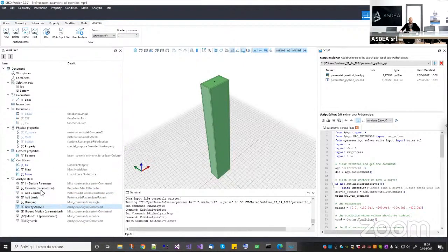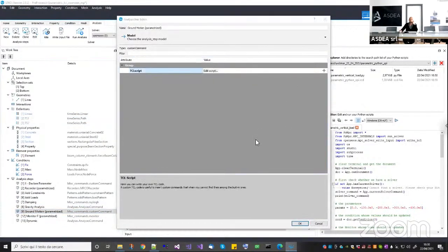Another change that I made is the ground motion, because the ground motion now should be parameterized as well, okay? So I cannot use the ground motion command, the uniform excitation command in STKO, because in STKO I have to statically give it a time series. Instead, I want to convert it into a custom command, which is very easy for the uniform excitation.